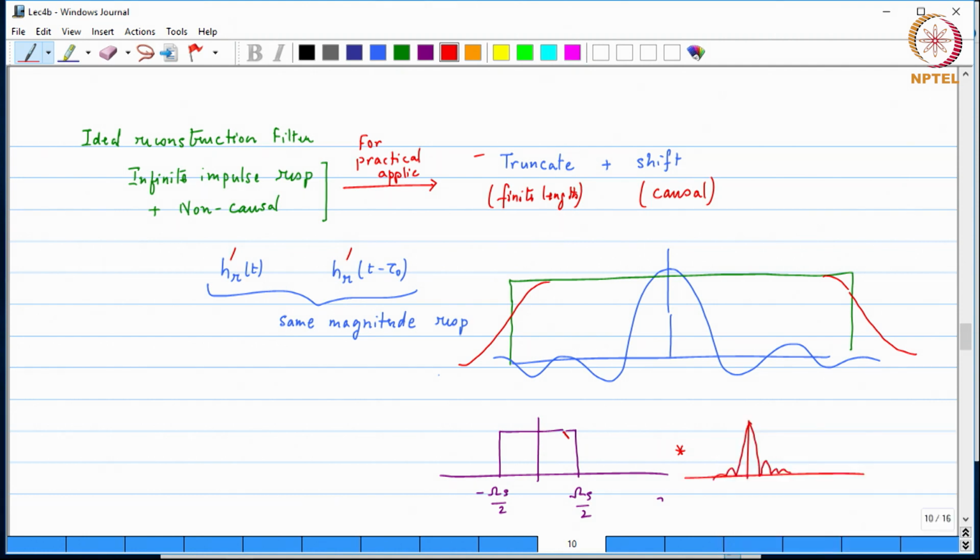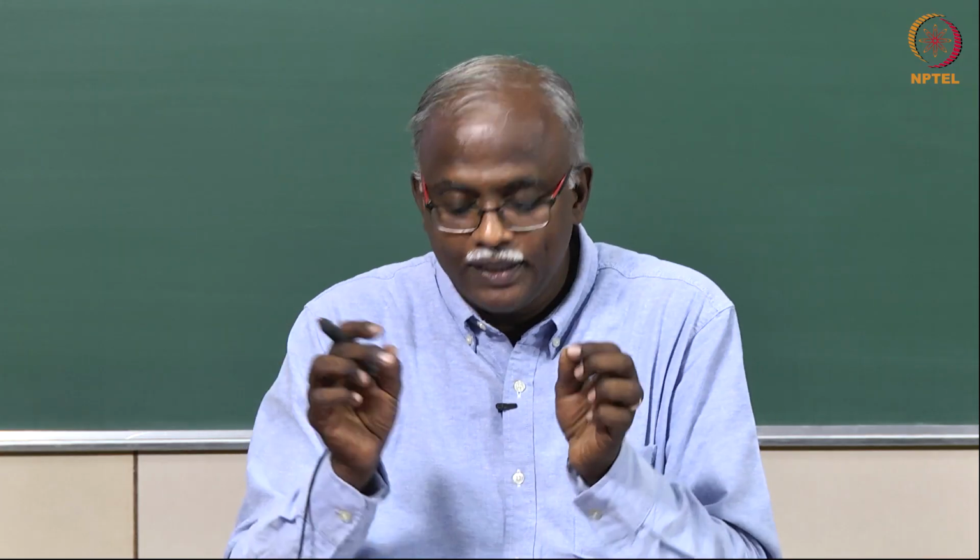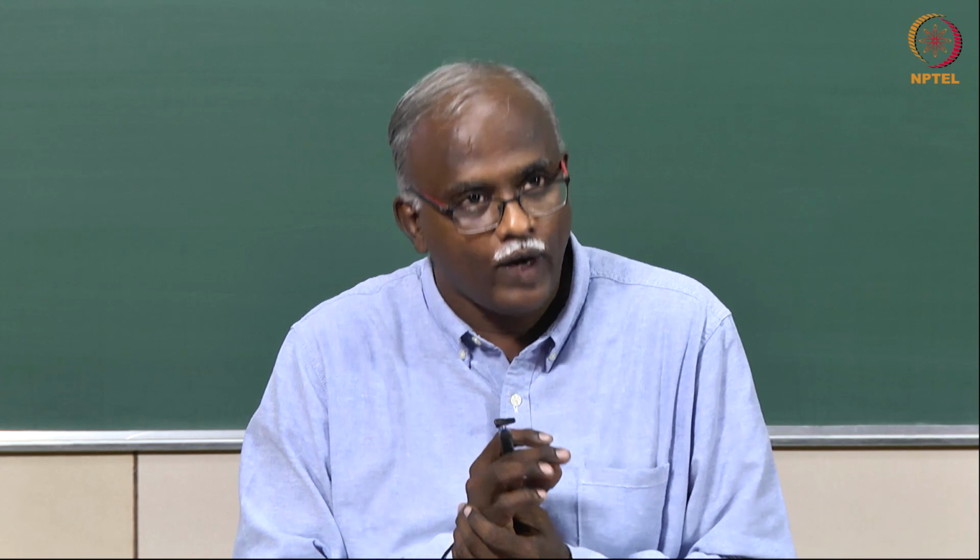Now, convolve these two, and what you find is a widening of the brick wall. The low pass property is retained, zero crossings are retained, the Nyquist property is retained because the windowing does not affect where the zero crossings occur, but the spectrum becomes a little bit wider.